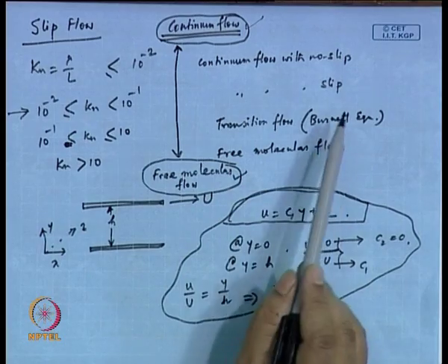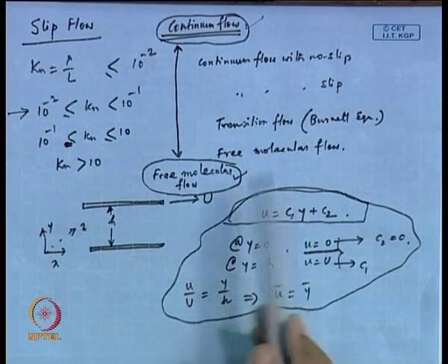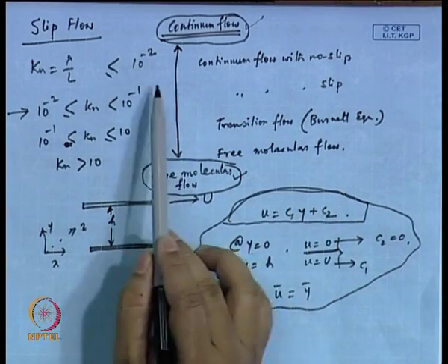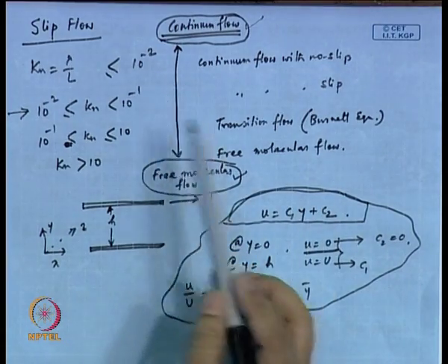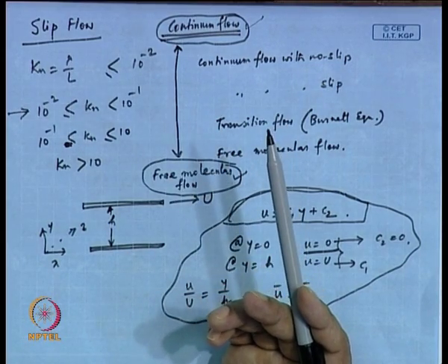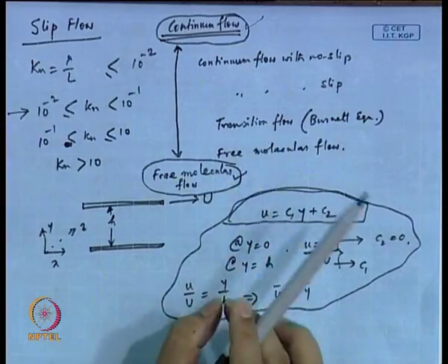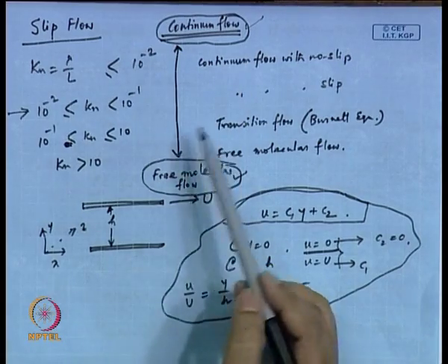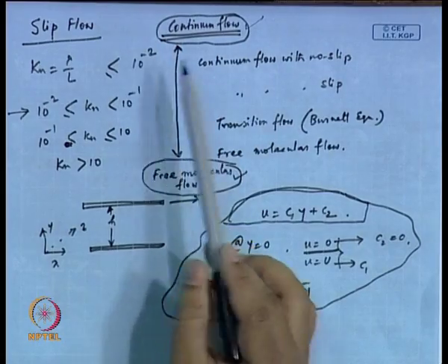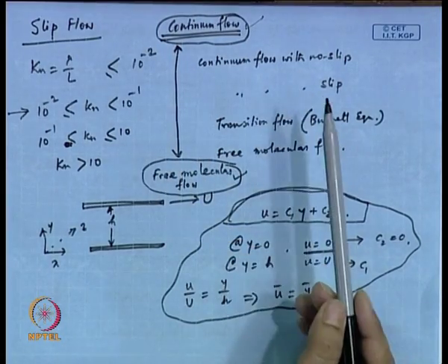Now, where does this slip boundary condition, or what we discussed today as first order slip, stand? That is basically what we call a make-do approach. You know that you are not doing the right thing. The rigorous thing would be free molecular flow, or the other rigorous thing would be continuum flow, based on which you are writing this Navier-Stokes equation.